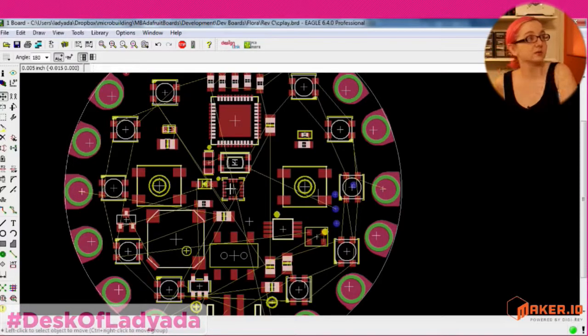Okay. Yeah, that was another question I saw: when you design this, do you think about the pick and place machine vision system? Not as much as I used to. I used to think it mattered, and then as I did more work with the pick and place, I realized it doesn't really matter as much as I thought. I used to think, oh, don't put these components too close to each other, give yourself spacing. But for the most part, you don't have to worry about that too much. Obviously make sure that mechanically it works. You can have huge parts next to skinny parts, but that means the skinny parts have to be pick and placed first. The flattest ones go first, then the bigger ones.